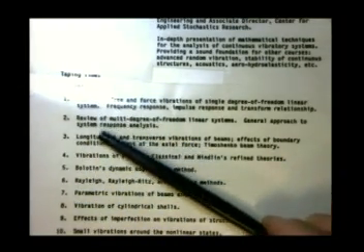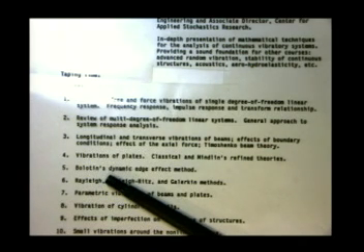Then, these are all exact methods that we talked about. But as we know, a system may have characteristics that change from one point to another. For example, the modulus of elasticity can change along the axis of the beam. Why could this happen? That is how systems are designed nowadays. In 1991, relatively recently, in Japan, they developed what are called functionally graded materials. Functionally graded materials are materials having a varying modulus of elasticity according to our desires.